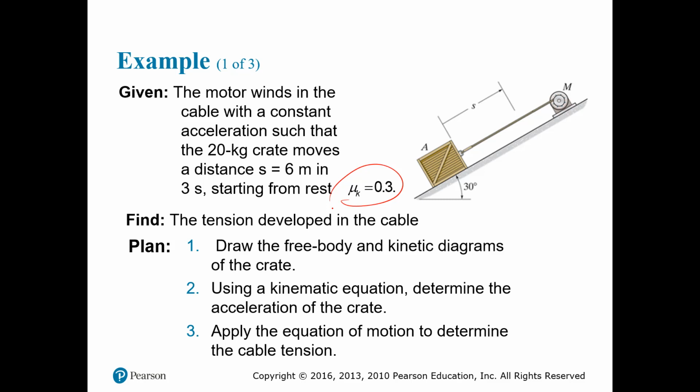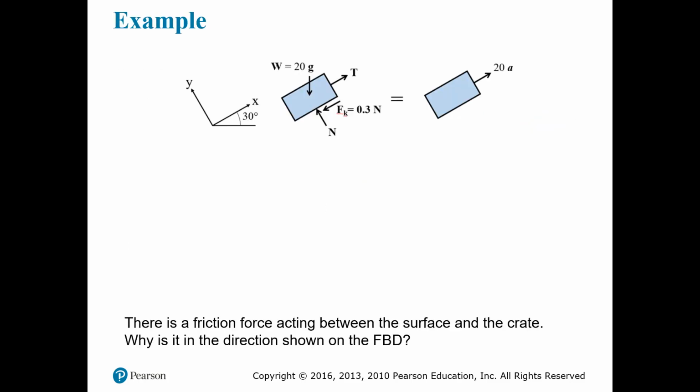And again, same thing. We use a free body diagram, then we use the sum of forces equals ma, and then we use kinematic equations if they're needed. Then after that, we can apply all of our equations in order to get the results we're looking for. If we take a look at this, the first step is to determine your x and y. In this case, x and y have been rotated with the same inclination you have in the exercise.